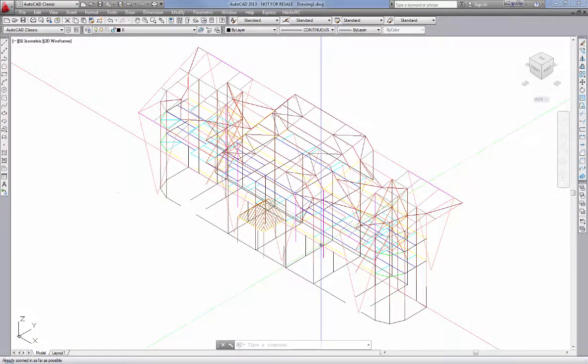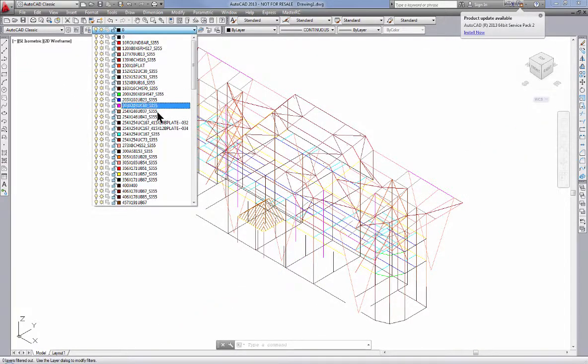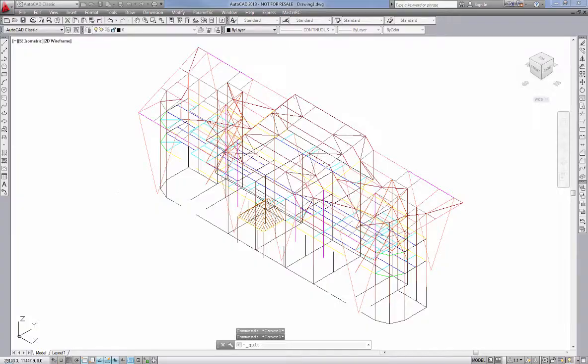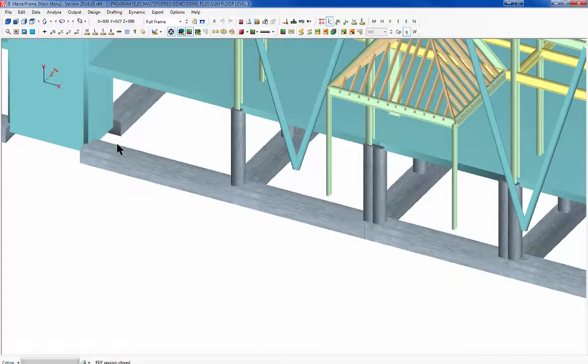Now the nice thing about this is that each layer is assigned to a color. Each color is a layer, a steel section size, so we can see all the different section sizes for use if we want. Now that's okay, but more important, I think, in the DXF area is the drafting area, where MasterCAD is very quick and useful.